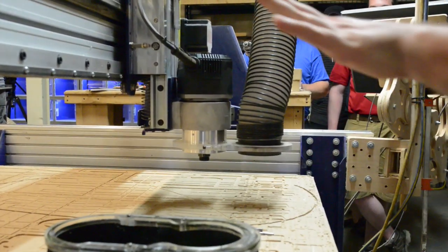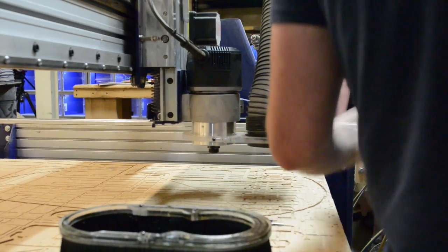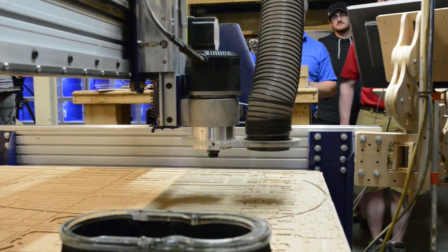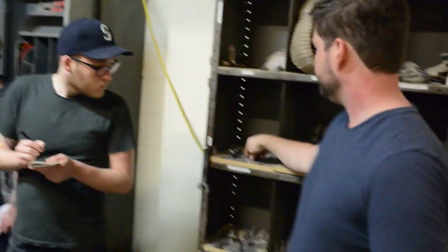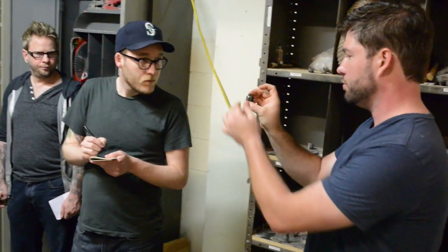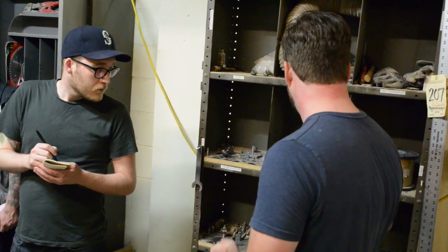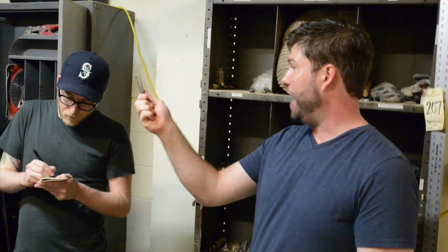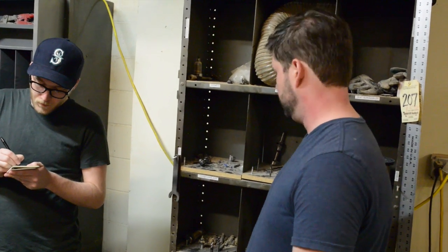So we're going to take that off. Now we need the collar, since there's nothing on here. Remember we talked about the different shank sizes? We've got the router bit itself, but then we have the shank that the router has to hold on to. Those are always over here. So you've got 1/4 inch, all the way up to 1/2 inch. If you have a big wide 1/2 inch shank, just grab the corresponding collar. Those will always be right here.